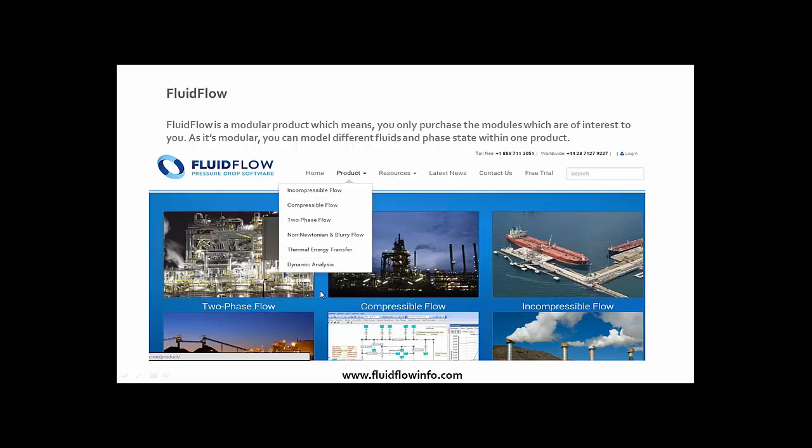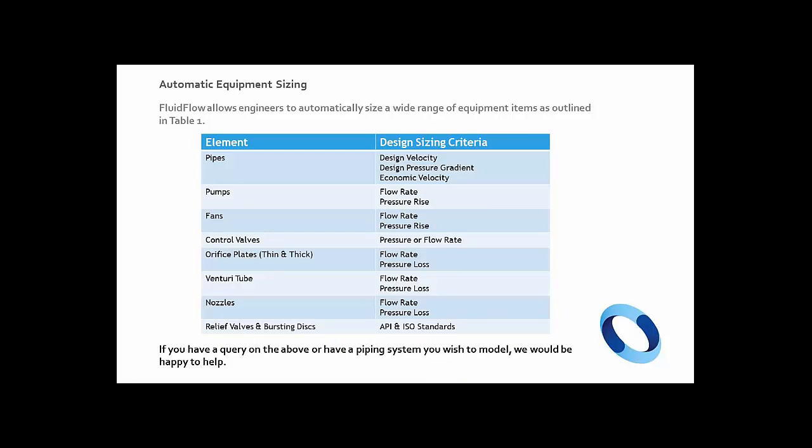scenarios and model your system as it performs in reality. Okay, so if I just move on to the next slide. So today's webinar session is focused around automatic equipment sizing and sizing of relief valves in particular, but let's just look for a moment to see what other elements we can automatically size within FluidFlow. So you can see we can size pipes based on either a design velocity, a design pressure gradient, or an economic velocity, which is calculated automatically by the software.